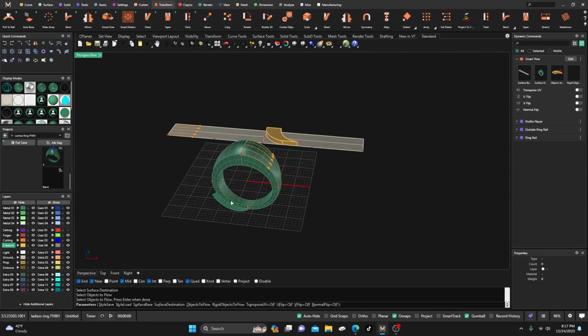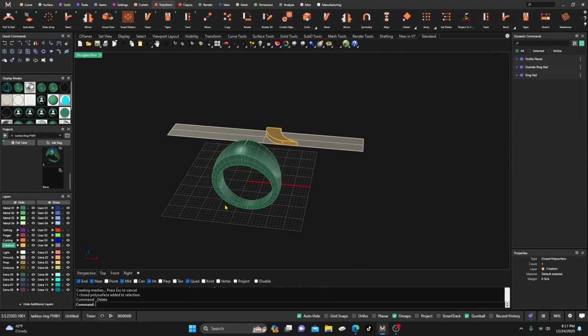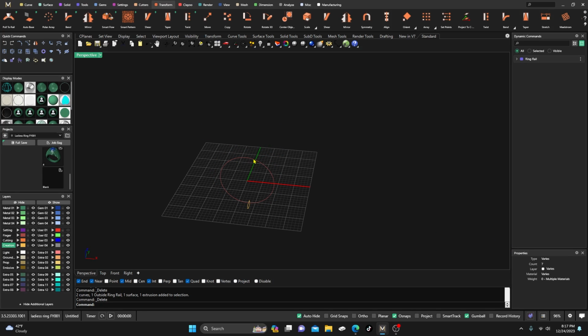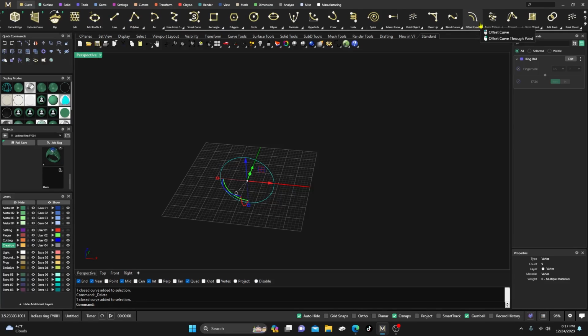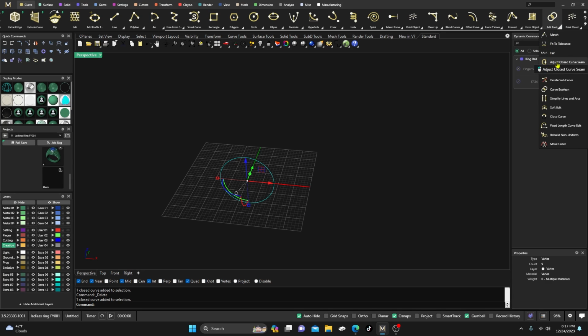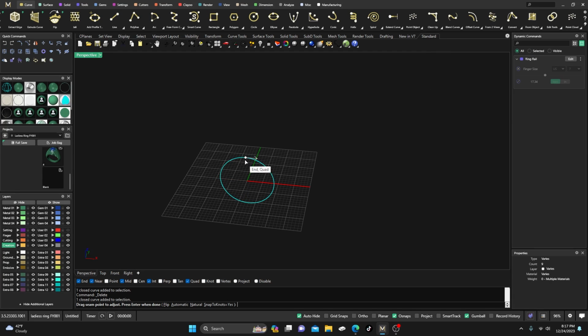Why? Because in MatrixGold, if I go back and get rid of all this stuff here real quick, and get rid of that, go back and check my seam. So go to curves, go to from object, and edit tools rather, and then adjust close seam. The seam's at the top, right? So there's an easy way to do that as well, and keeps it parametric.